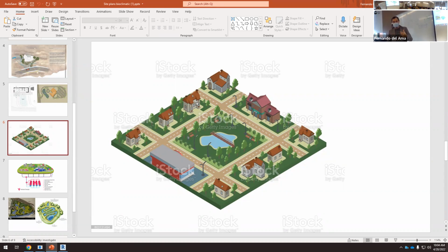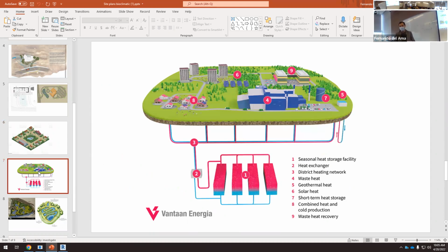And probably all the solar collectors placed on the roofs of this neighborhood. In summer, we don't need this amount of hot water. So if we connect all the solar collectors to this pond, the temperature of that pond will increase during the summer, and then it will be enough to use this warm temperature in winter. Okay, so that's the concept of heating storage. And as you can see, it always works with small neighborhoods. It doesn't work for a single family house, but if we have a neighborhood and all the buildings are connected to this mass of water.